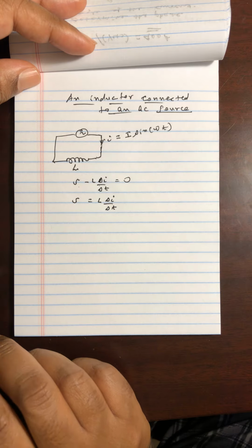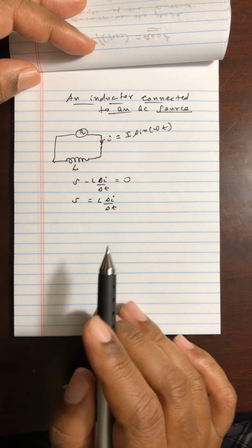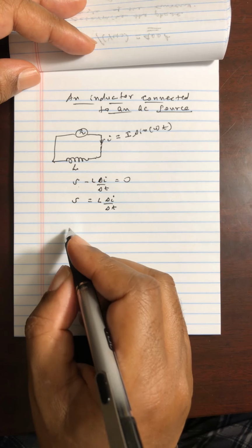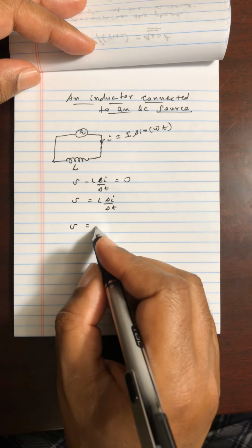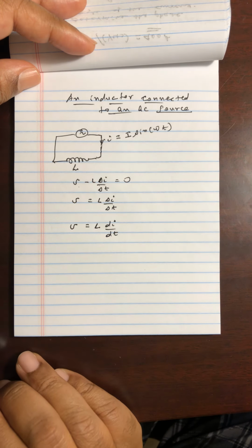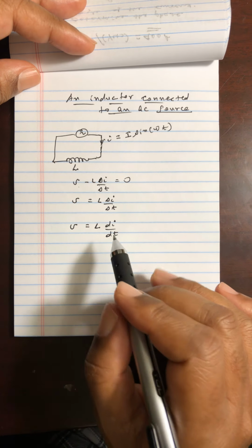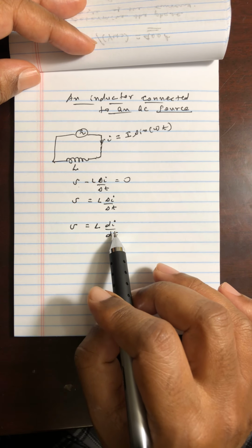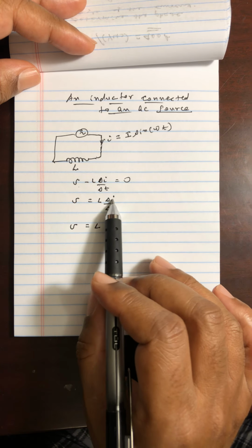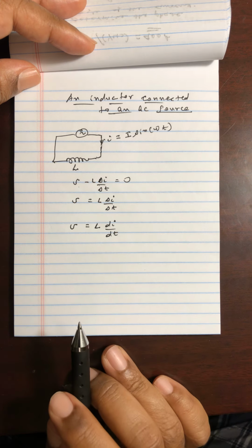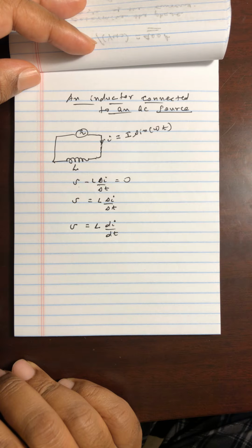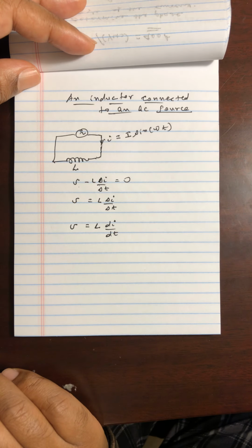Now I cannot do this without using calculus, so I'm going to use the derivative for this one. We're going to let delta T go to 0, and then we have the following relationship: the voltage equals inductance times rate of change of current with respect to time. For those of you familiar with calculus, as delta T approaches 0, this basically becomes the slope of the tangent line of the graph of current versus time, or the derivative. But don't worry about it, I just need to use it to do this.